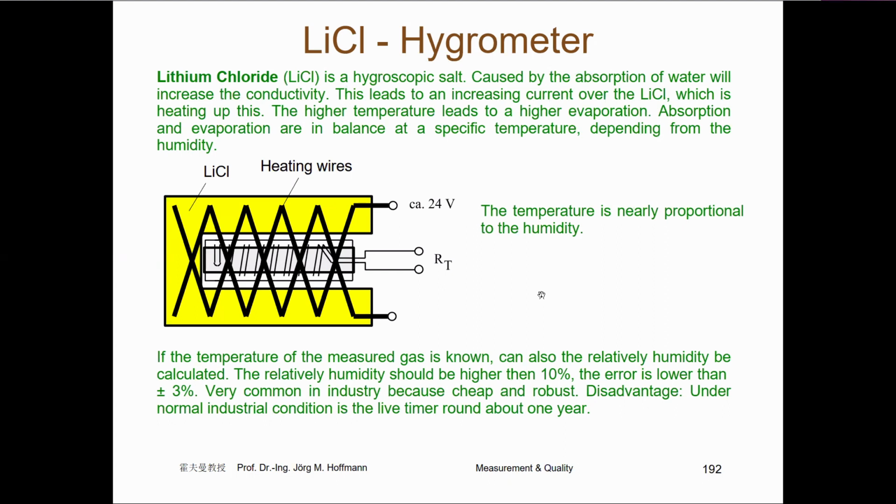They all have a limited working time, because when you put the sensor in humid air, you also have dusty particles in the air and so on. What is especially terrible is when you have kinds of oil or fat or something which closes the sensor against the humidity. That is a problem.